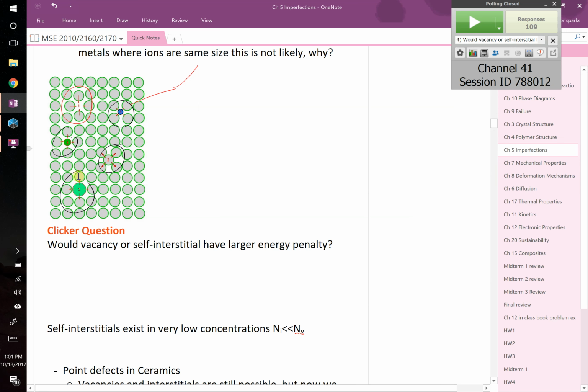All right, then you've got 4 and you've got 5, and those we would call impurities, right? They're different types of atoms. They're different sizes. One is too small and one is too large. Both of those cost the system energy, right? The strain field around that impurity is either going to be in tension or compression, and compression always costs more energy, okay? To push atoms, to squeeze them together, costs more energy than to be pulling them slightly apart, right?